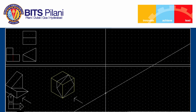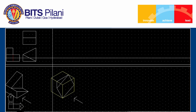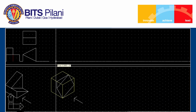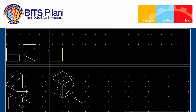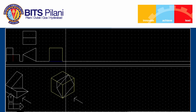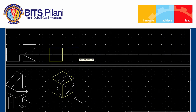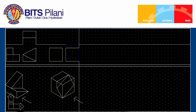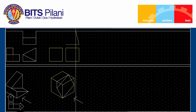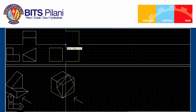So, it is again 4 by 4. For the side view, we will leave one grid space between the side view and front view, and between the front view and top view also we will leave one grid space. So, always follow this practice to ensure the alignment between the views of the object.